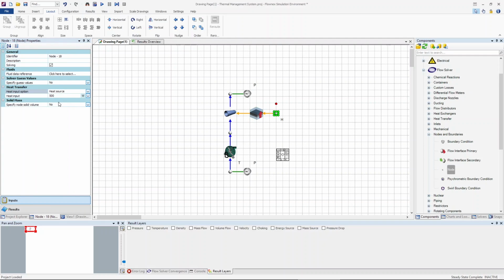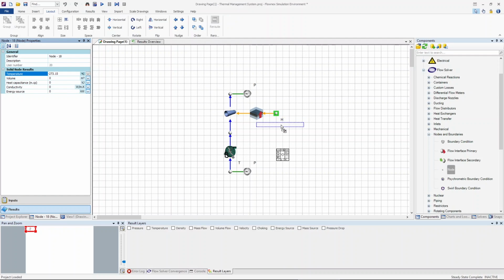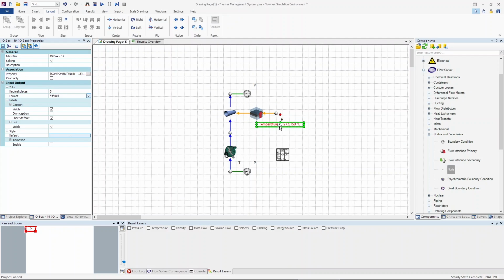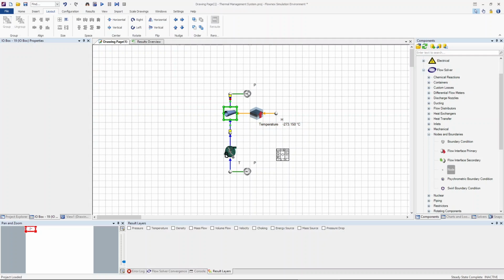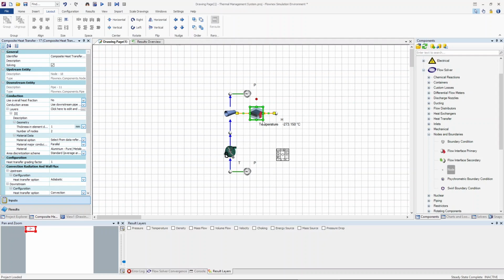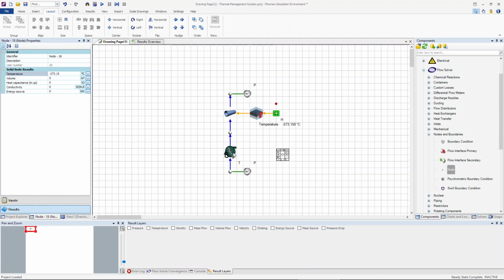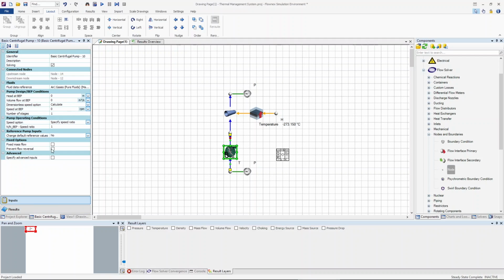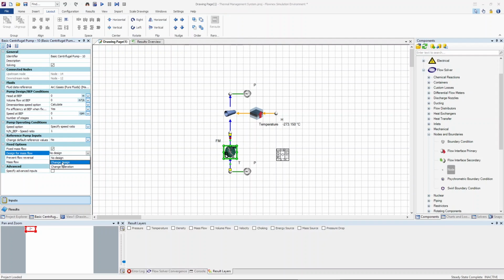So the temperature of the fuel cell stack, which we are quite concerned to keep constant, will be represented by this node's temperature, for example. So we have to define the nodes, the boundary conditions, the flow channels, the heat transfer element, and also the heat being generated. And then lastly, we can design for the fan, and essentially we can fix the mass flow and change for design.